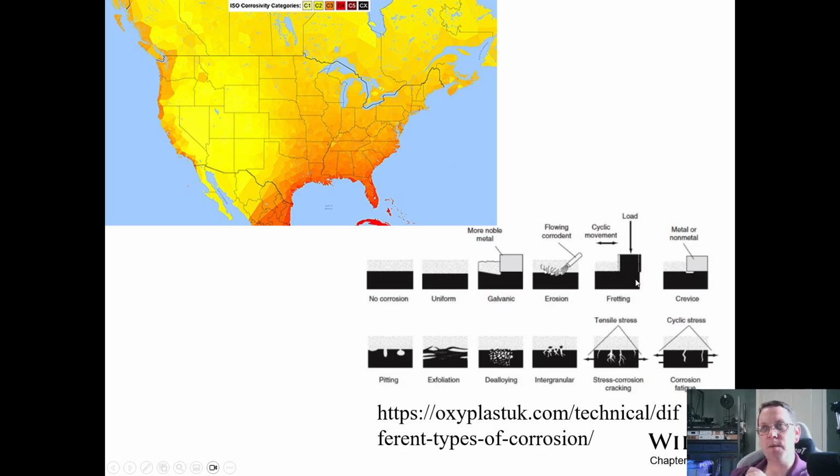So that one's a little bit less common for what we see, but you can also have metal, non-metal, and you have crevice formation at the interface between those, especially where you get pooling liquids and things that help facilitate that. Pitting, so generally removing material and creating typically sort of circular pits in nature. Exfoliation can be layers peeling off of the top, just like named for the exfoliation of skin and skin cells, things sort of sloughing off the surface.